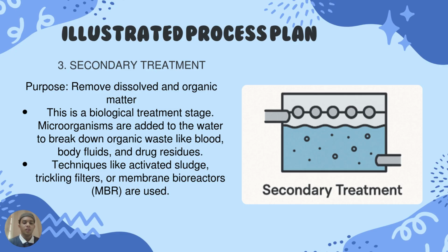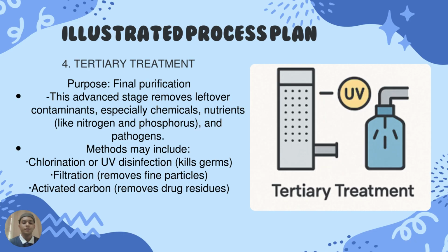Secondary treatment. Its purpose is to remove dissolved and organic matter. This is a biological treatment stage. Microorganisms are added to the water to break down organic waste like blood, body fluids, and drug residues. Techniques like activated sludge, trickling filters, or membrane bioreactors (MBR) are used.